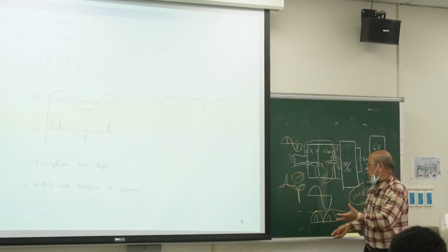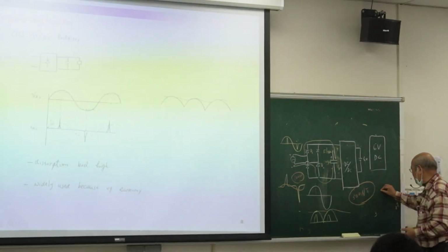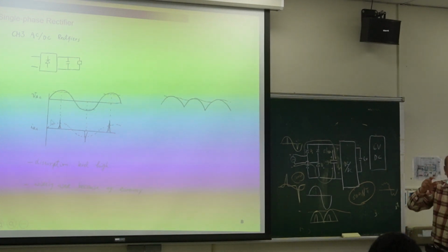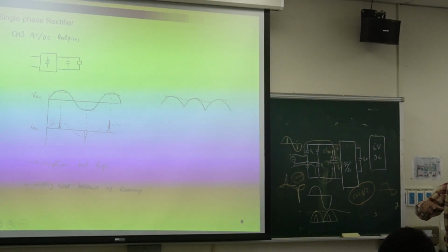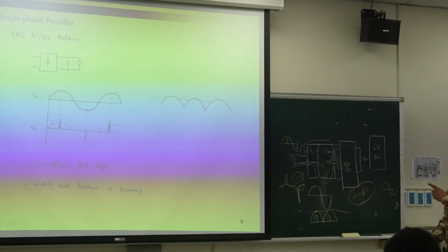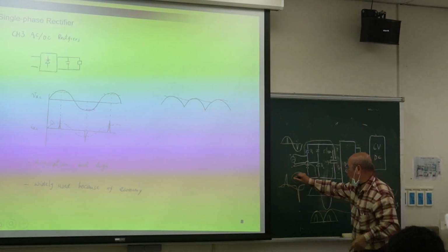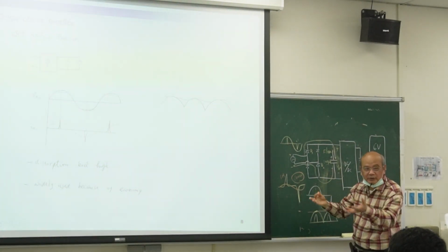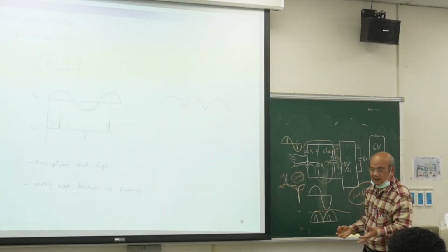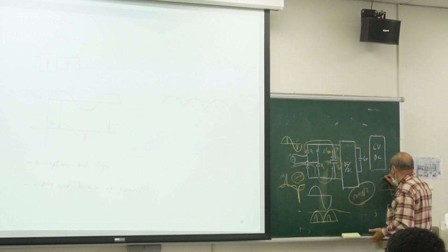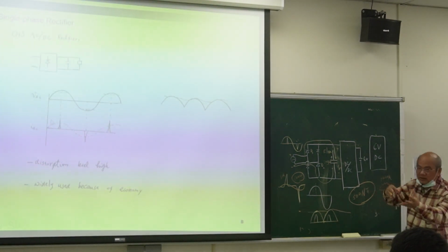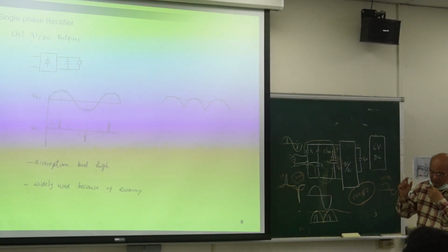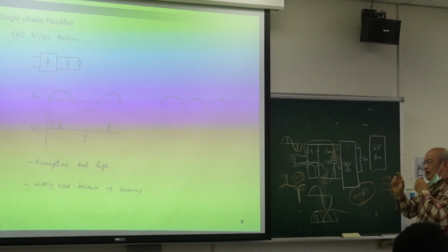You can see the whole building, the current becomes like this. They can disturb the utility, right? Because if only one ampere, I'm happy. But now it is 1,000 in this building. Then the current becomes 1,000 ampere harmonics flowing everywhere. Then Taipower company is not happy.